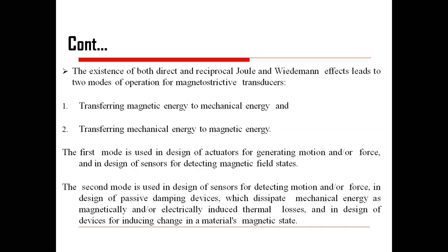design of the sensor for detecting magnetic field. It means when you bring a magnetic field near to the sensor, either it will actuate, and the circuit will open or the circuit will close depending upon its operation, whether it is normally open or normally closed. If it is normally open and you bring that magnetic field near it, then it is going to become closed. If it is closed, then it is going to become open.